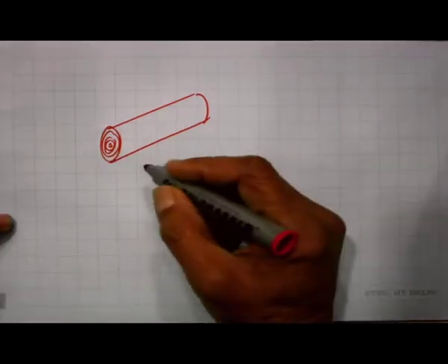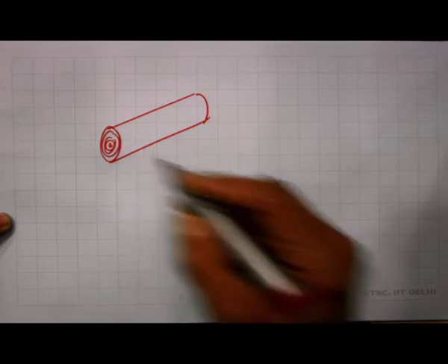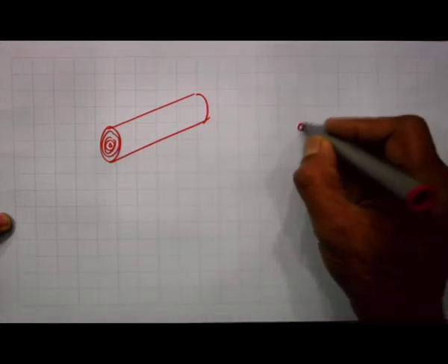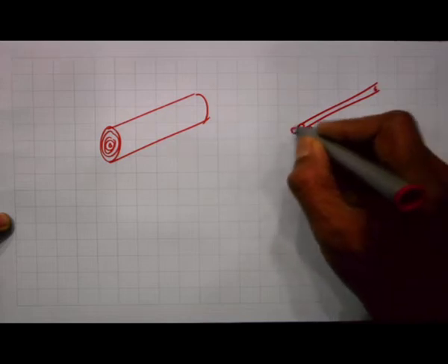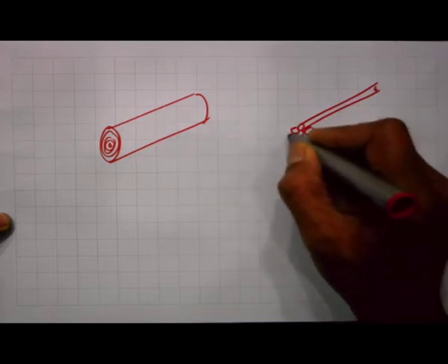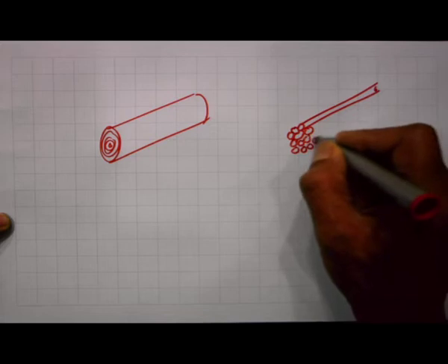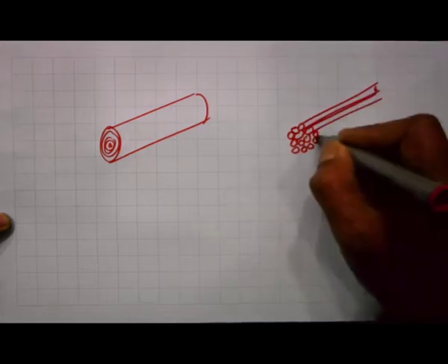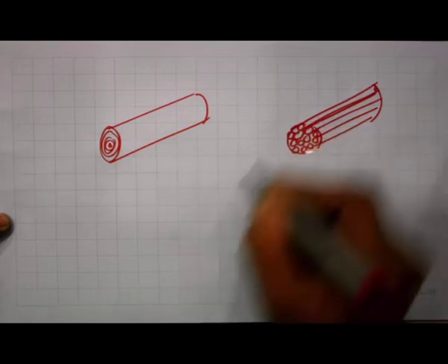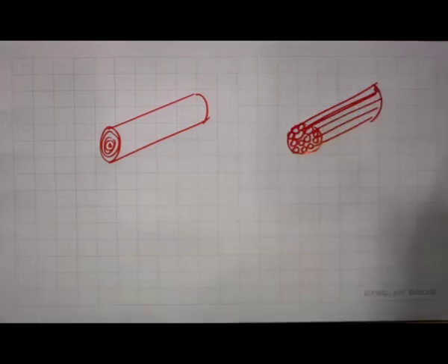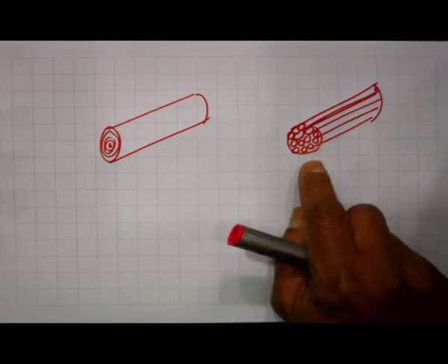I can actually reduce this effect by using what is called lamination. So, if instead of a single piece, I take a larger number of these cylindrical rods of smaller diameter, forming the same overall diameter as before, then the eddy currents have no path to get completed, and so the amount of eddy current generated in this situation becomes much reduced.